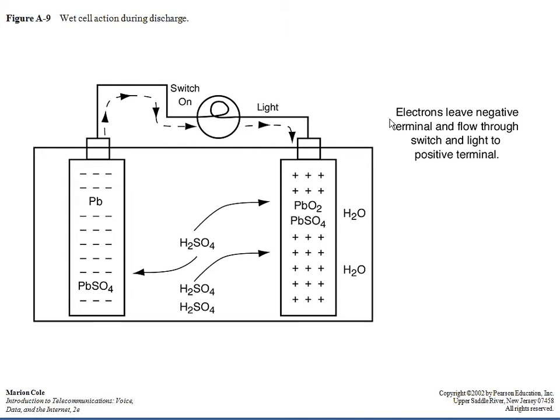The negative electrons from the lead end on the cathode, the negative terminal, flow through the wire, through a lamp and filament, making it glow, and deposit themselves on the positive terminal end. Now, as this reaction goes on, as more electrons travel that path, the positive end becomes less and less positive, and the negative end is becoming less and less negative. They're becoming more neutral, or back in balance. And when we've completely discharged that energy, the battery will no longer conduct electricity in this way.